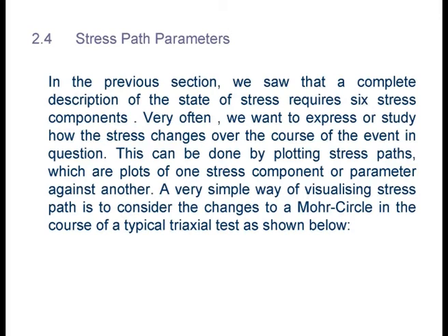A lot of engineers in Singapore, when you tell them stress path, get scared off because it seems something very mysterious and hard to understand, but actually the idea is very straightforward. You already know that in order to get a complete description of the state of stress in a 3-dimensional medium, you need 6 stress components.